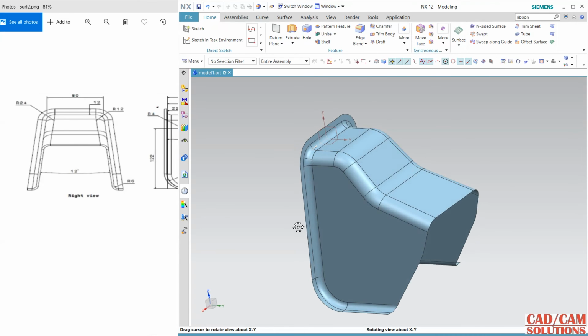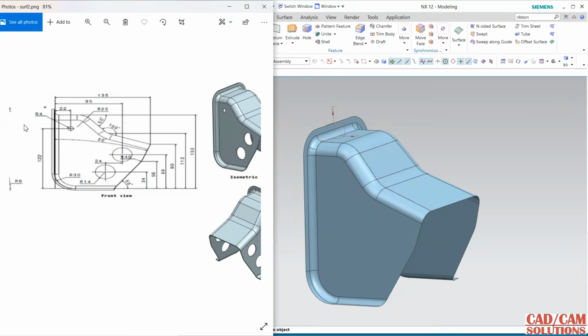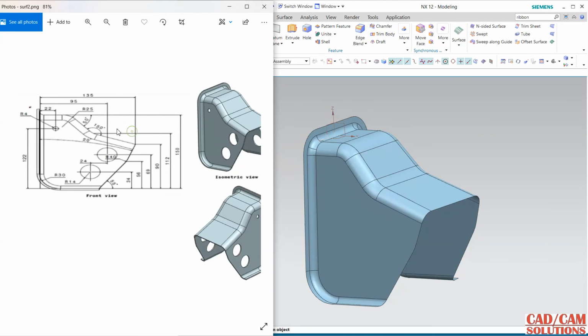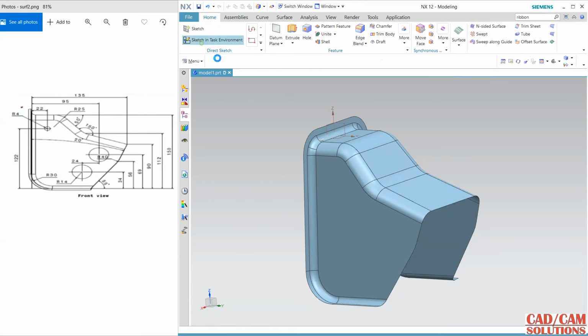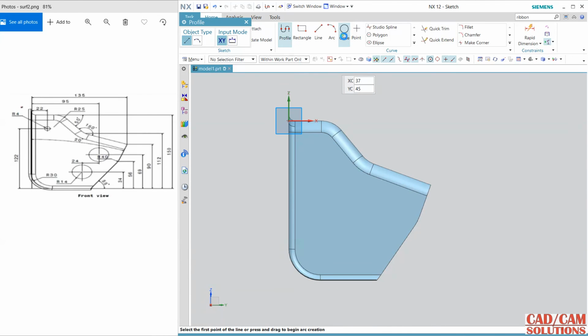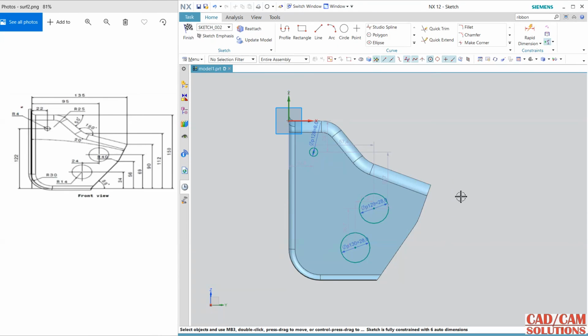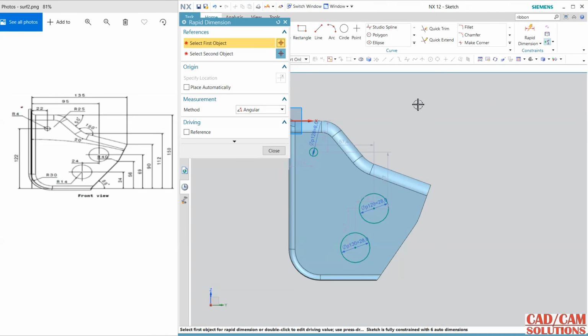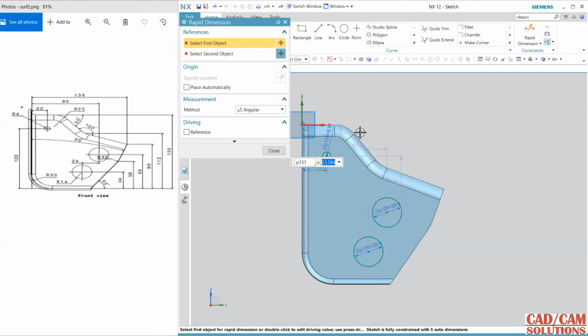Now I'm going to cut the holes, the remaining holes. For these holes, I am using the circle command. So go to sketch. This middle one is my working. Okay, circle, click one smaller circle with 4 radius, 8 diameter, and here we have 14 radius, 28 diameter, one and two. Now the dimension, and for the dimension this gap is 22.